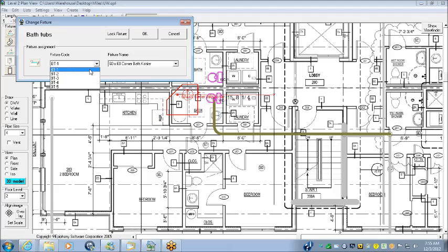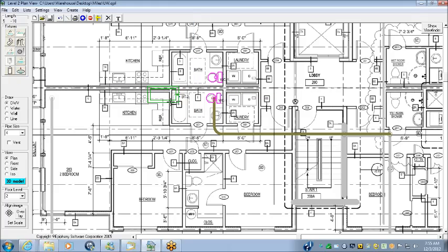It's a corner tub. We'll change that to a tub shower, which is what's indicated on the plans. And so we drop down to a 2-inch and connect that, add a lavatory over here. And we'll circle the back. And that would be a good wet vent arrangement under the International Plumbing Code.